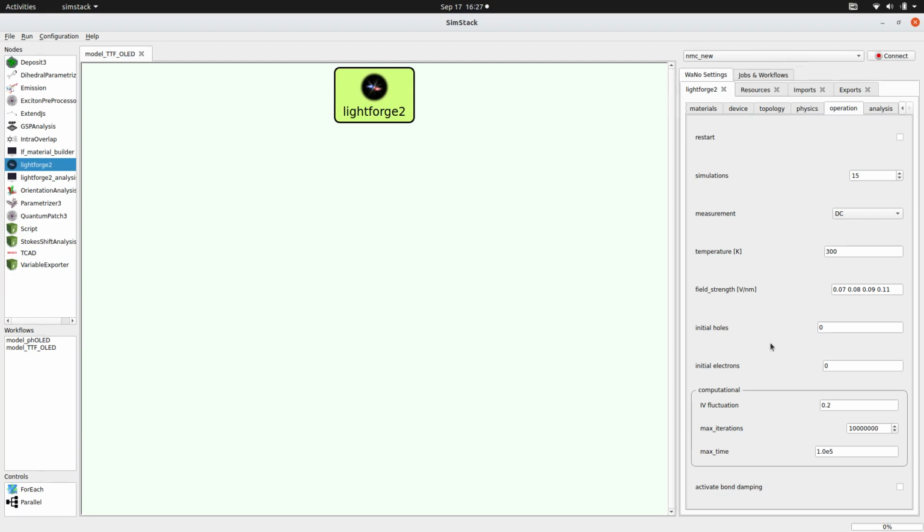And now finally we have to set up the termination condition for the simulation. So we can set a maximum number of iterations to 600,000. For different kinds of OLEDs which are less efficient due to higher barriers between layers or deeper traps, more simulation steps will be needed, for example by a factor of 10 more, 6 million or 20 million. This depends strongly on the device setup.